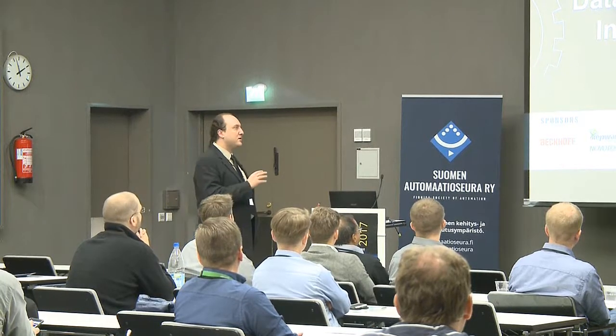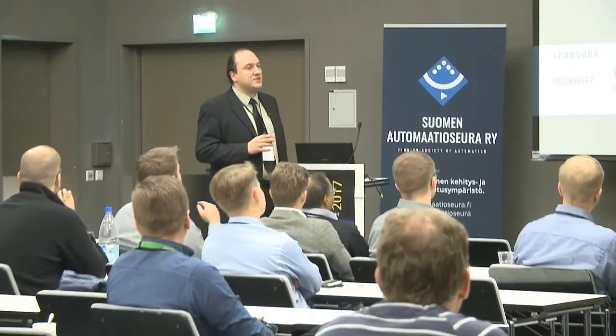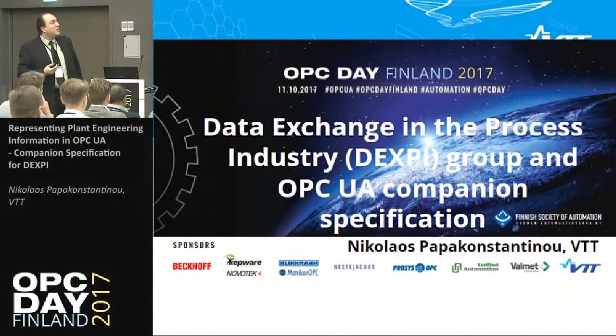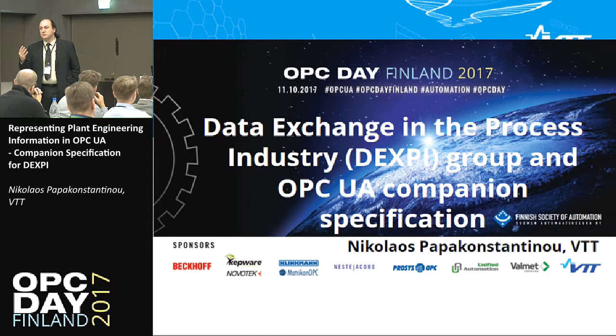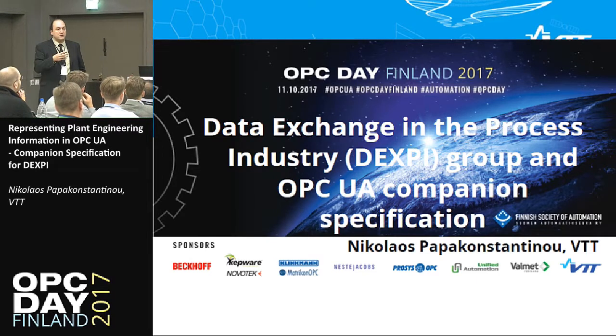So I think that maybe the common theme of the presentations until now was using OPC UA to talk to machines from a higher level, or how machines can talk between themselves if they are from different vendors. But the OPC UA meta model is much more flexible. It doesn't always have to do with communication to machines or between machines. It can also model other kinds of information that is relevant to the factory.